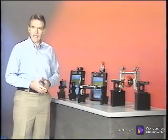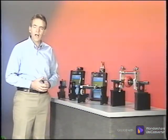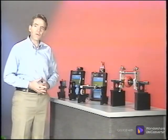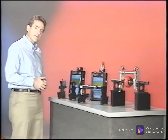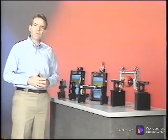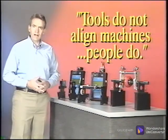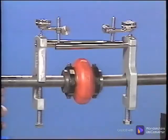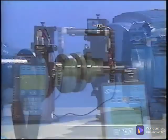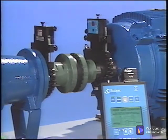If you were to hire a contractor to align a machine, would you get better alignment from a dial indicator set that costs a few $100s, or a laser set that costs tens of thousands of dollars? The key to remember is, tools do not align machines, people do. The tools are merely used to measure the alignment condition, and some tools help calculate the machine moves. But the better tools help a competent person to perform the same job faster and with less risk of error.